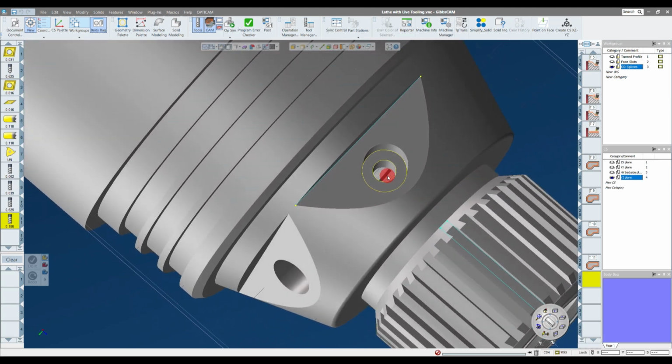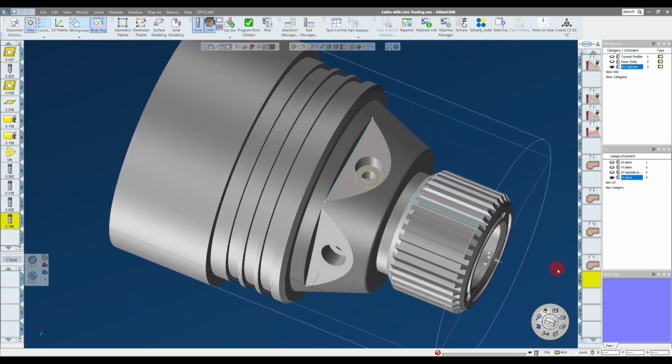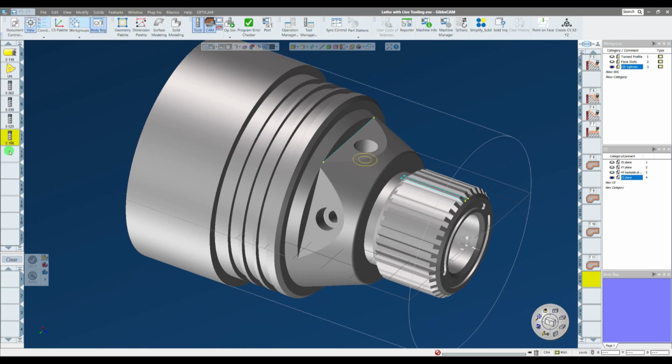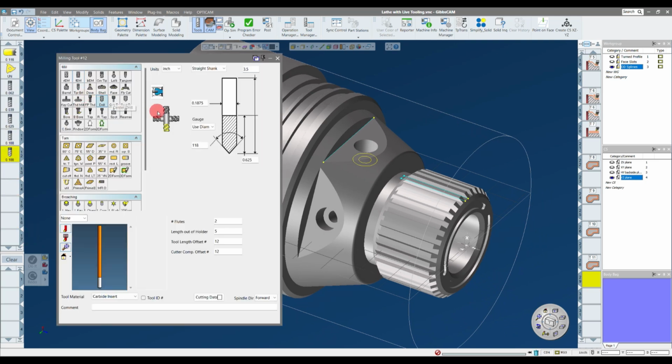And let's work on the last feature of this part, which is these through holes. So I'm going to go in here and create tool number 12, and that's going to be a drill. Again, it's 4 millimeters in diameter, so I can hit 4 and click on I. Because we'll use this as a 140-degree carbide drill, it's going to have a designation of times the diameter with the length. So let's go 4 times 5 times D equals, and then automatically convert that, oops, that was 20, back to inch. So it's a bit over a 3/4 inch length of cut for this drill.